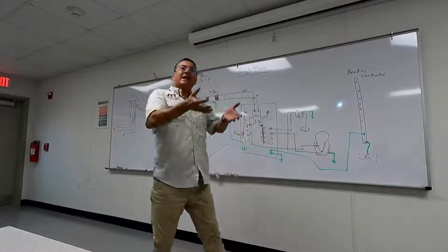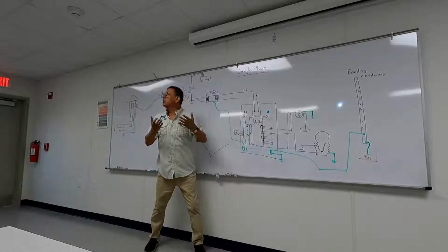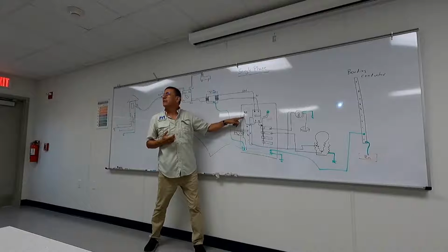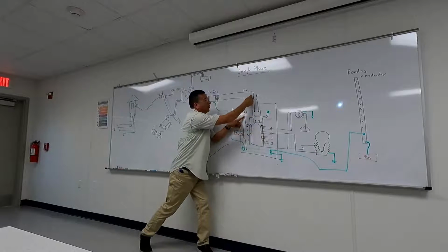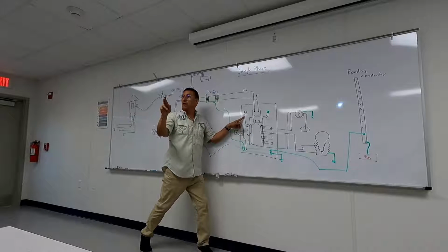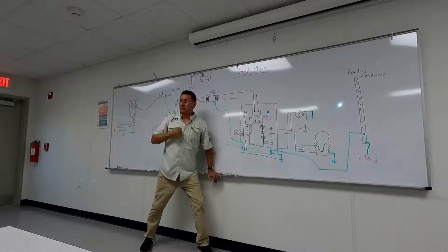Now I am in the situation that I have the reverse polarity on. Why? Because the neutral enters in the hot and the hot enters in the neutral. I switched those cables, correct? All right, now my neutral is hot.